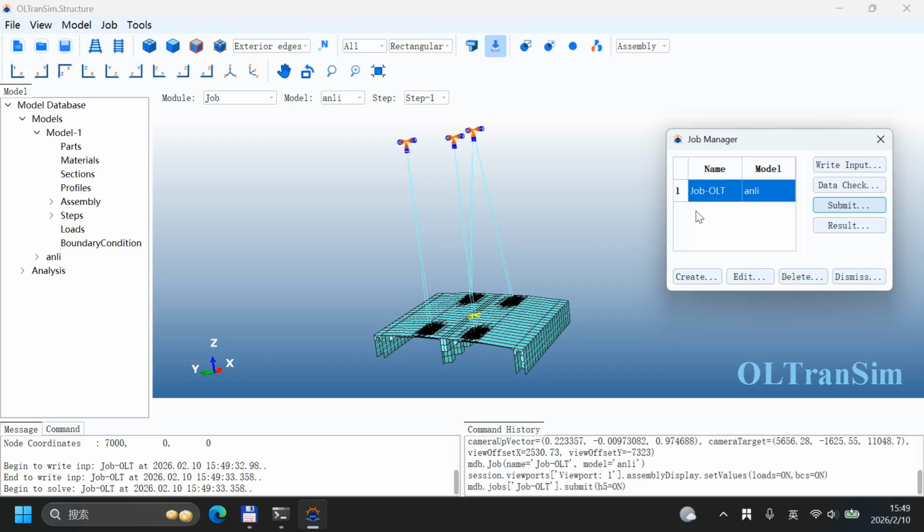So I will say something about this model. I think it's symmetric from left or right and top and bottom. So if we don't add this boundary condition, this structure could move around the xy plane and from this way or this way.